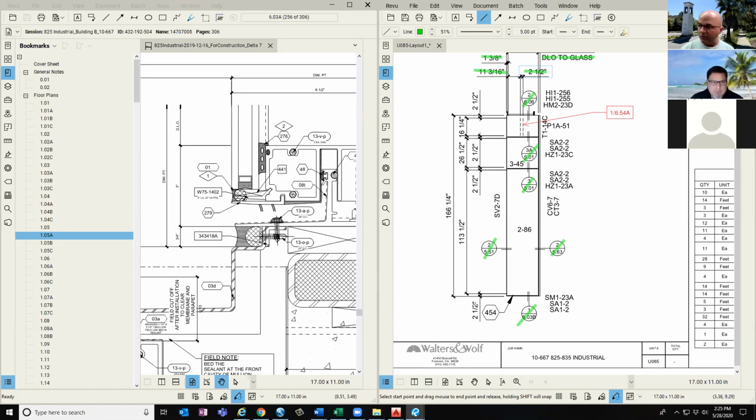My unit drawing is showing 2.5 inches, and that's a byproduct of this coming in out of Revit. So I have to understand that the Revit insertion point is usually 7/16 below the bottom of this sill member, and that's based on being able to place the families in correctly. And now when the takeoff program reads that, it's going to give me this dimension, which is based on the Revit insertion point. So I'm going to agree that this 2.5 inch dimension is correct, even though I don't see this anywhere on the actual detail. It's a background that I have to know in order to verify that that works.